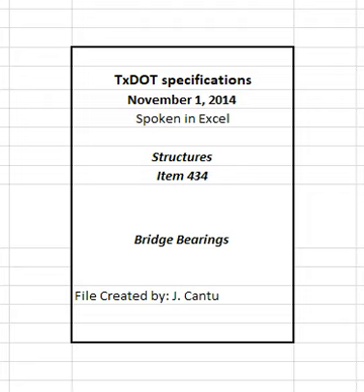Provide the remaining surface, outside the stainless steel sheet interface, flat to a tolerance of 1/16 inches in any 24 inches. Attach the stainless steel sheet to the steel top, sole, plate by continuous fillet welding around the edges with an approved welding electrode. Do not extend the weld above the sliding surface. Protect the sliding surface from weld spatter. Polish the stainless steel sheet to a bright mirror finish less than 20 micro-inches RMS, and solvent clean to remove traces of polishing compound after attachment to the steel plate.